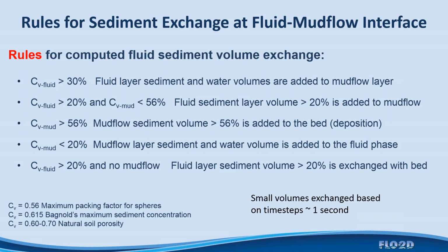I mean, if you're going to do two-phase flow, you might as well do it for a small feature and do it in 3 dimensions, and there are some models out there that do that. But you're not necessarily going to do a better job computing the overland flow, flood inundation, or where a mud flow starts and stops using a lot of very highly variable lift and drag coefficients and viscosity variations, as well as inhibited fall velocities from particle collisions in a very detailed model like that. It's just too complicated.